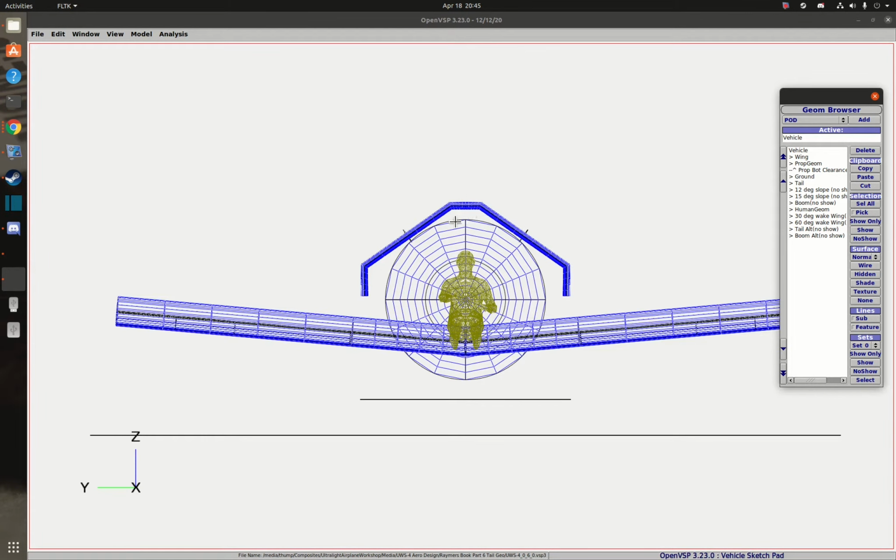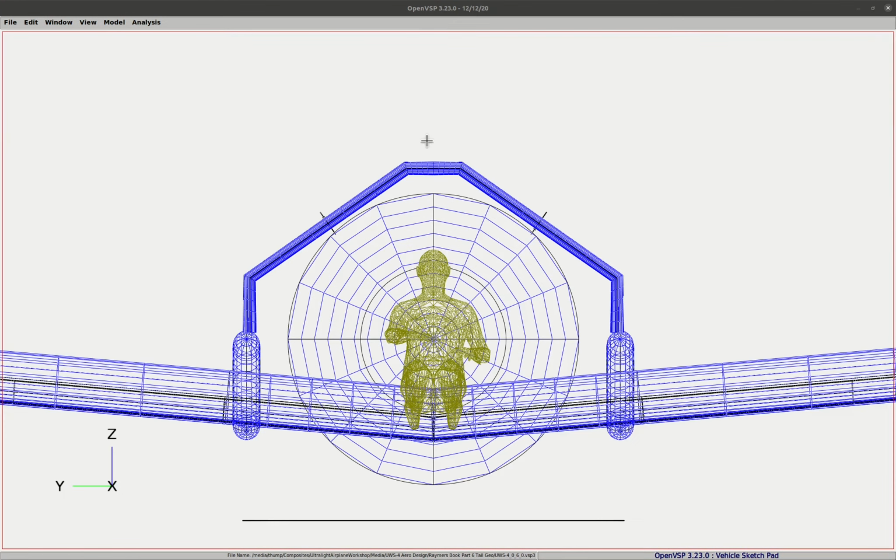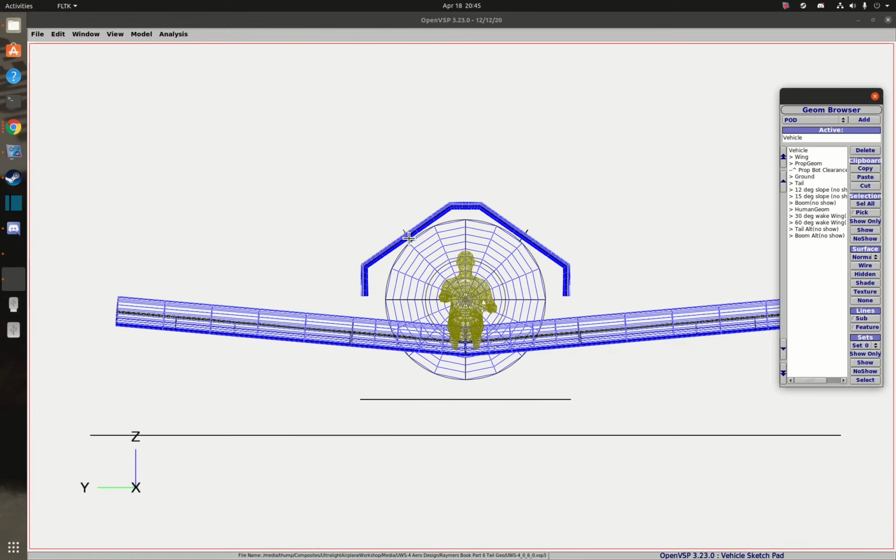I've also put a little bit of a span here to hook these two together. When you push forward on the stick, both the control surfaces from these two angled parts of our tail will come down. And I wanted to have enough space here that those two trailing edge corners from these control surfaces would not hit each other. So that's how I came up with this distance here. Now initially I did not have these vertical parts on here.